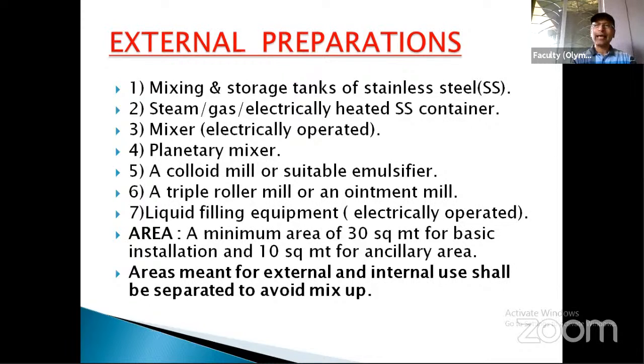Mixing and storage tanks, and keep in your mind that all these equipments are to be made of stainless steel 316 grade. Different grades of steels are available, but our GMP specifically mentions that not below the 316 grade of stainless steel will be allowed in the manufacturing unit for maintenance of this GMP.